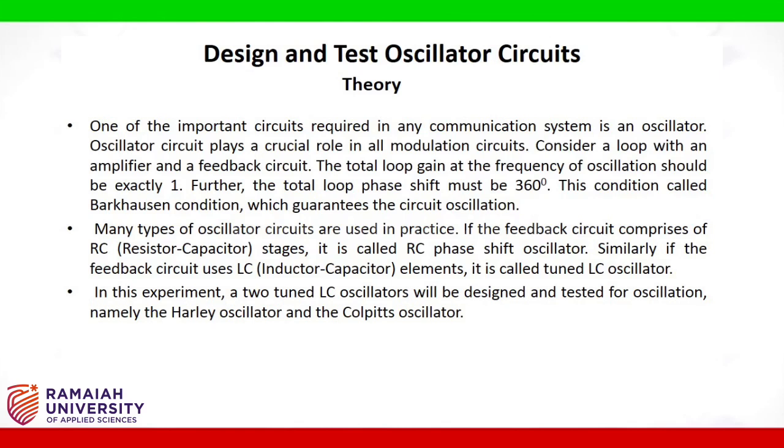Many types of oscillator circuits are used in practice. If the feedback circuit comprises RC, that is resistor-capacitor stages, it is called RC phase shift oscillator. Similarly, if the feedback circuit uses LC, that is inductor-capacitor elements, it is called tuned LC oscillator. In this experiment, two tuned LC oscillators will be designed and tested for oscillation, namely the Hartley oscillator and the Colpitts oscillator.